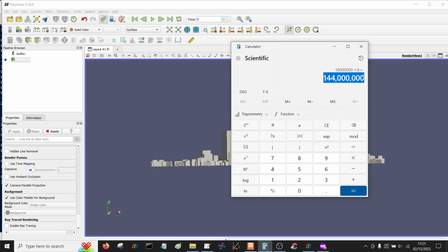So half meter cells everywhere over that domain size, and you end up with 144 million. And I have run several cases of lattice Boltzmann solver like that one. If you want to go to quarter meter cells, times by 8 again, and you've got a mesh size of 1.152 billion, which is doable.